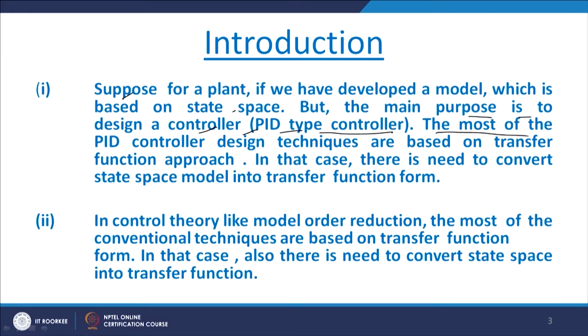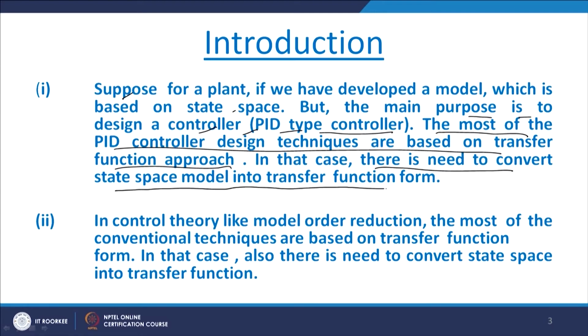Most of the PID controller design techniques are based on the transfer function approach. Researchers have developed various tuning techniques, that is tuning of PID control parameters, and they are based on the transfer function approach. Therefore, in that case there is a need to convert the state space model into transfer function form.